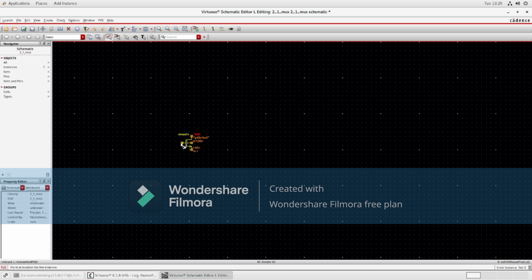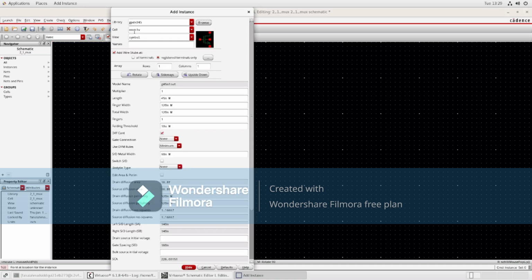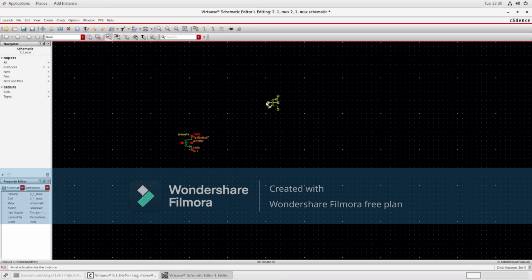We'll place NMOS here, and for deselecting this, press escape. Now let us select the PMOS. We can write here as well, just replace N by PMOS 1 volt, and we will select our PMOS over here. Okay, so this will be our PMOS. We'll place our PMOS over here.